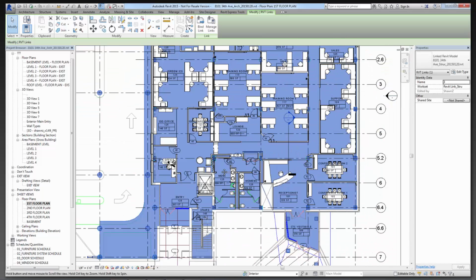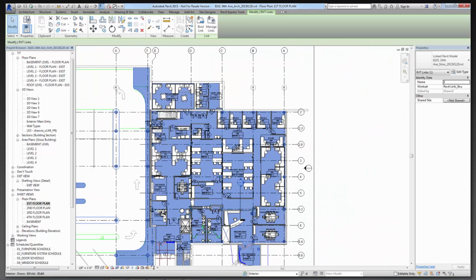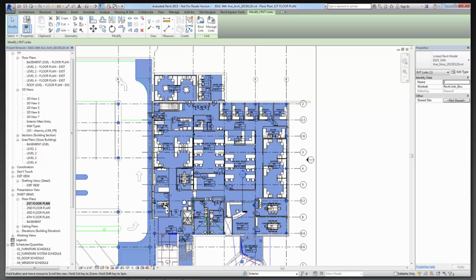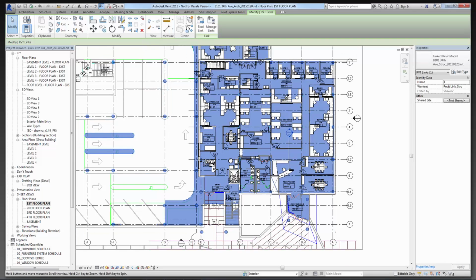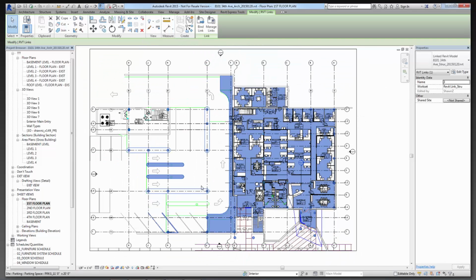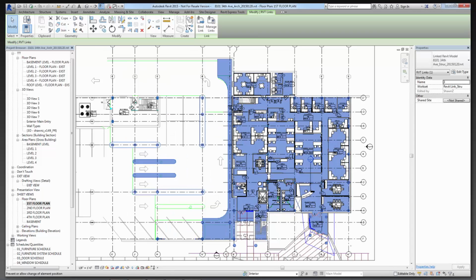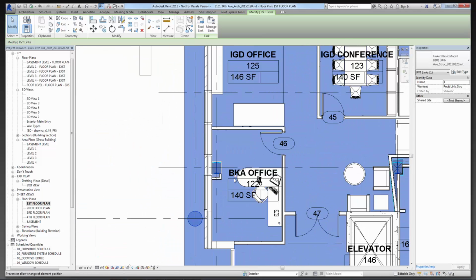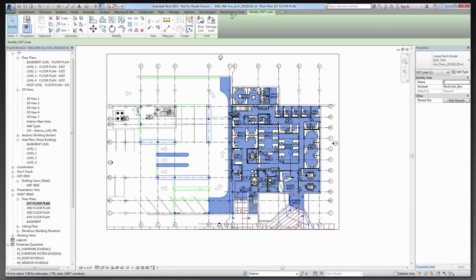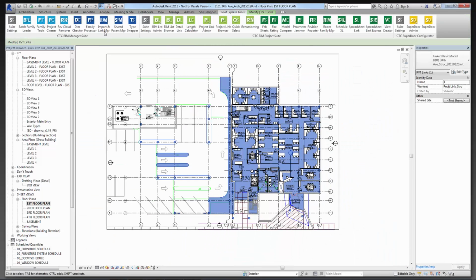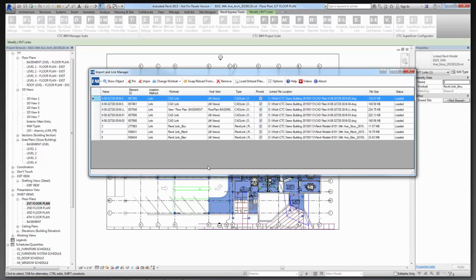And if I zoom out here, I believe this is also pinned. I'm not seeing the pin out there. Oh, I have the ability to unpin it, therefore it is in fact pinned. So I pinned this from that dial. There's the pin right there, little graphic for the pins in the middle of the overall boundary of this structural model. But yeah, it's been pinned, and all of that was managed here from the Revit Express Tools Import and Link Manager.